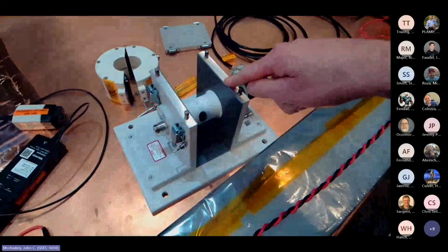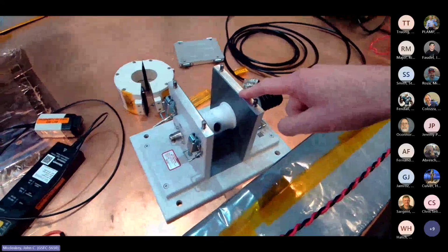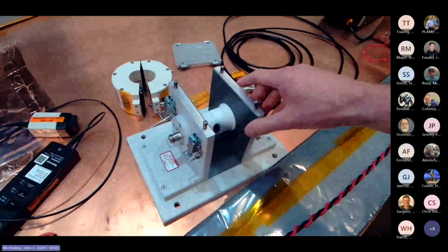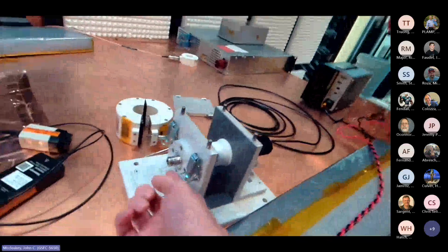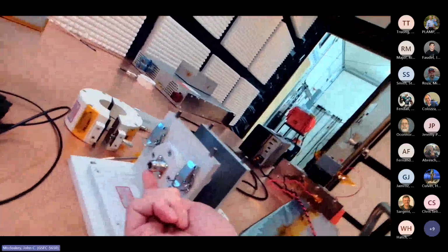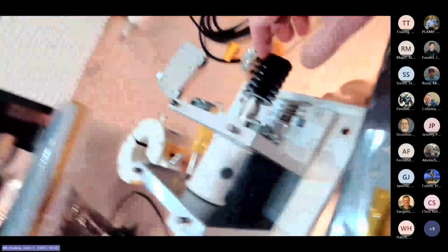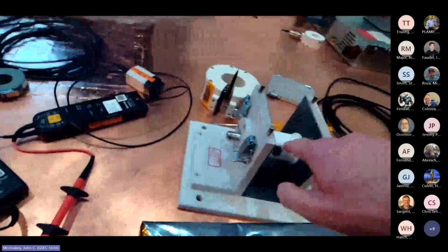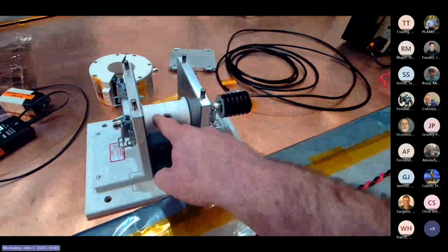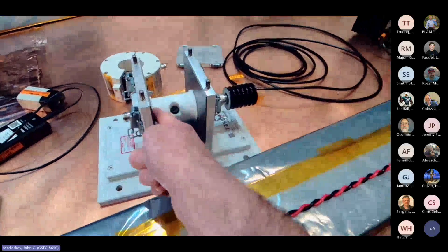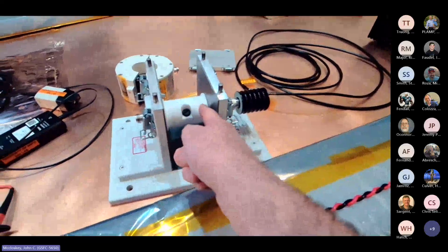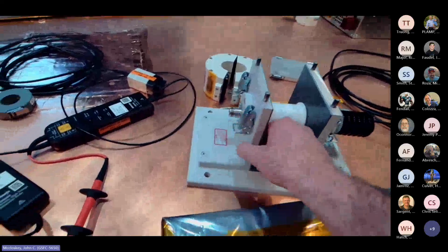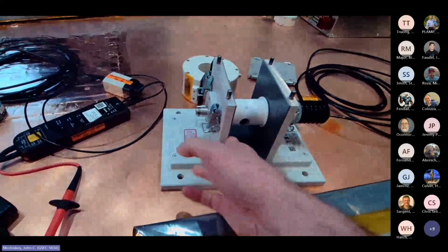And then here's the calibration fixture. So we talked about that. This will be one of the center pieces of what we'll be demonstrating, but I'll give you a sneak preview. It has a pair of N-type coaxial connectors on either end. This side has a 50 ohm dummy load on it. The center conductor of the coaxial connector feeds through, and it's got this isolator wrapped around it, but there's a fairly hefty conductor that feeds through, and then the shield of the coaxial connector connects to the base, to the structure, of the fixture itself.